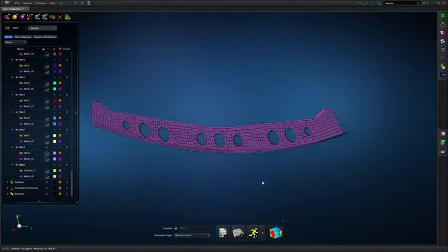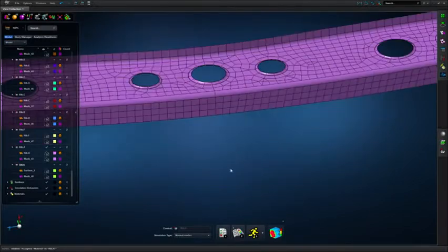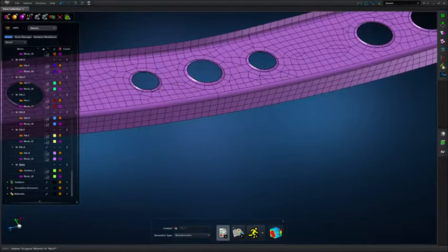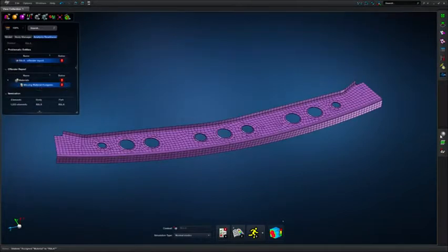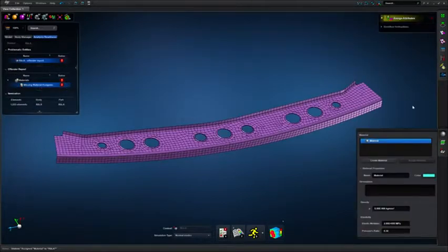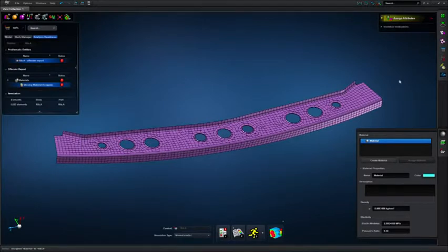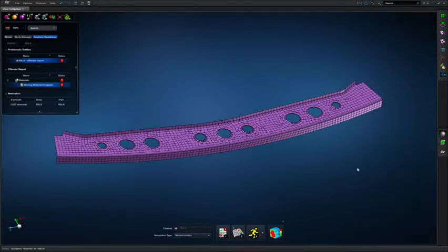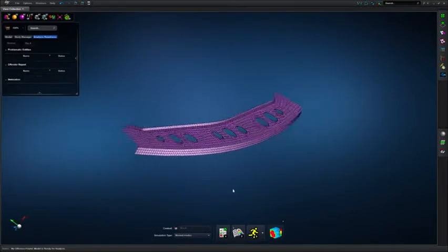Before moving up to an assembly and an entire analysis, I should make sure that this particular part is ready for analysis. I can do a quick check to spot any problems in just this part that may prevent a successful analysis. And we can do this because the application is integrated with solver methods. A quick check shows that I have neglected to assign a material. I remedy the problem, and a recheck shows that the model is ready to be analyzed.